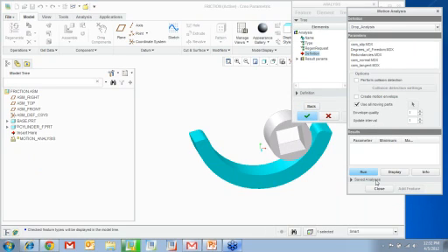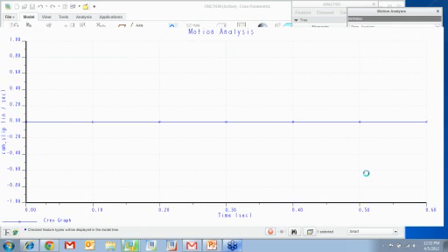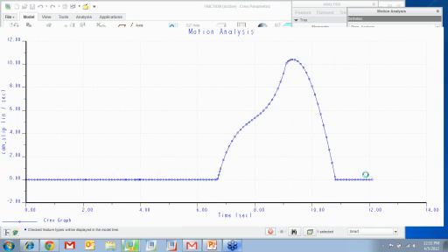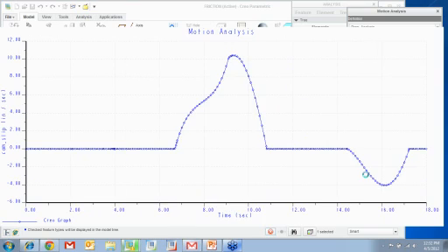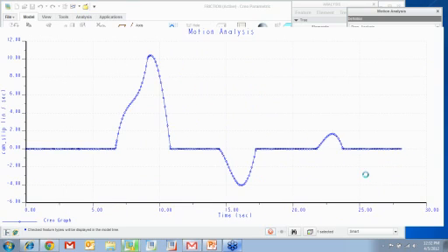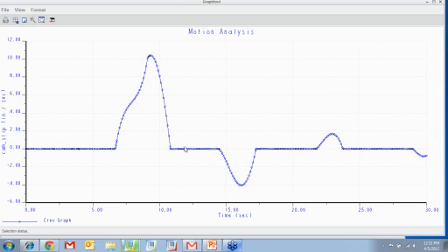See, you have a drop analysis right here, and you go ahead, run it, and it shows you how the cams kind of slip. So we have a motion analysis which says minimum and maximum are around 4 and around 11.